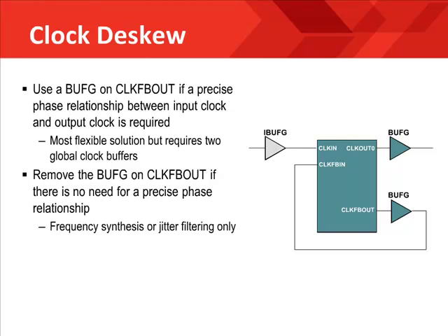But in the end here, what's happening is we come in through a dedicated clock pin. That's what's denoted by that IBUFG primitive. This will drive to the MMCM through a clock input port, and then our output, our desired clock, is routed globally on a BUF-G. And the clock feedback out, as I mentioned, you could use a BUF-G if you care about syncing up those clocks, and that would be used to feed back the clock to the clock feedback input.